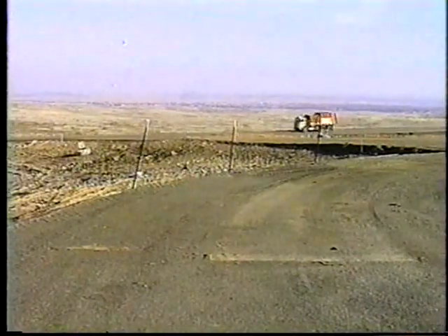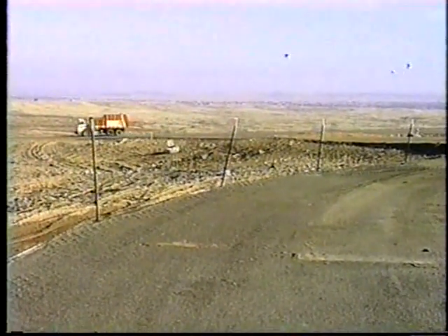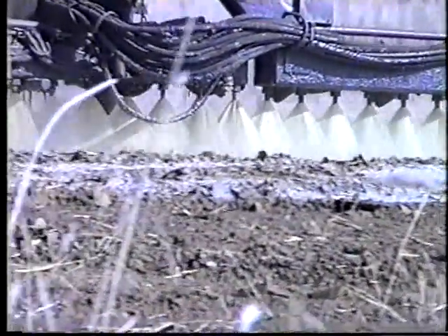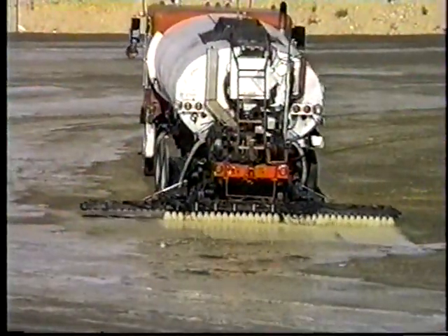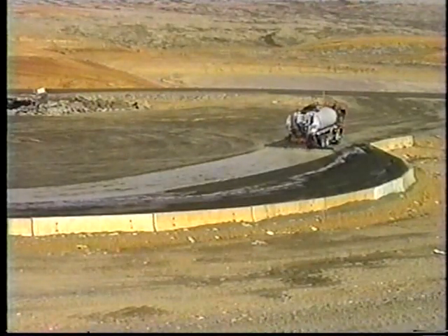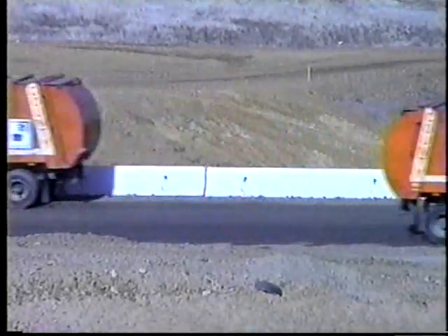Some people think the state of California sets the world standard for aggressive environmental regulation. In Sacramento County, home of the state capital, environmental suitability is indeed a serious issue. When it came time to select a treatment for road maintenance and dust control, road oil was the only product that satisfied both environmental and operations staff. Road oil is applied on landfill roads on an as-needed basis, and it provides year-round service, holding the road surface and providing dust control in dry weather and sealing the surface off from moisture penetration during rains.